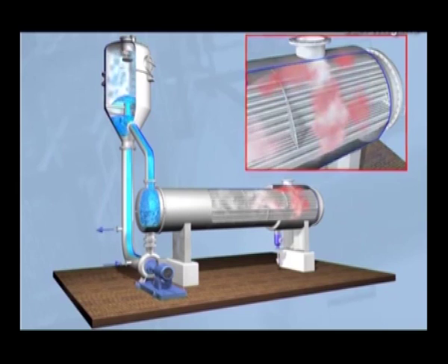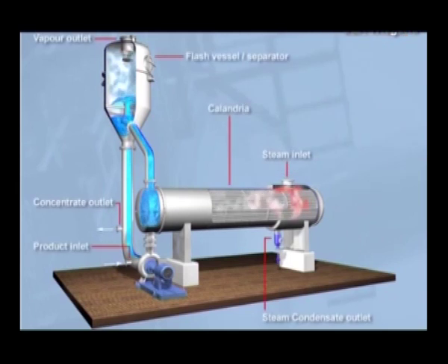Only part of the total evaporation occurs in a given pass. Forced circulation evaporators are well suited for heat sensitive material, fruit juices especially, because the loss of flavor is involved as they get exposed repeatedly, although the temperature is low, by maintaining the high vacuum.